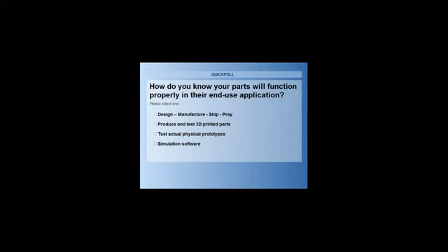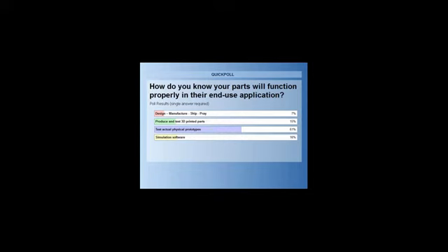Compression molding. No, flow simulation can't be used to model that, but that has been coming up quite frequently in our plastic injection molding software. So you could potentially do that. Can I set up Excel to drive an automated optimization? So you wouldn't use Excel. You could do design tables inside of SolidWorks, or basically our parametric study is an Excel file, so you could cut and paste the values from your Excel file and then use them.